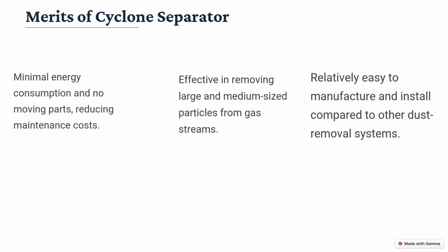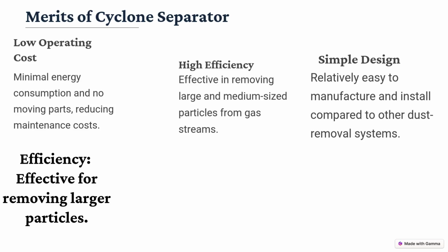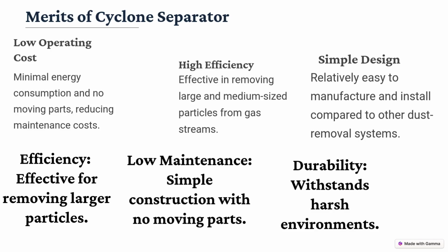Merits of the cyclone separator: low operating cost, so it requires minimum energy consumption and has no moving parts, reducing the maintenance cost. Then high efficiency, effective in removing larger and medium sized particles from gas streams. Then simple design, relatively easy to manufacture and install compared to other dust removal systems. Then low maintenance and simple construction with no moving parts, and it is durable, withstanding harsh environments.